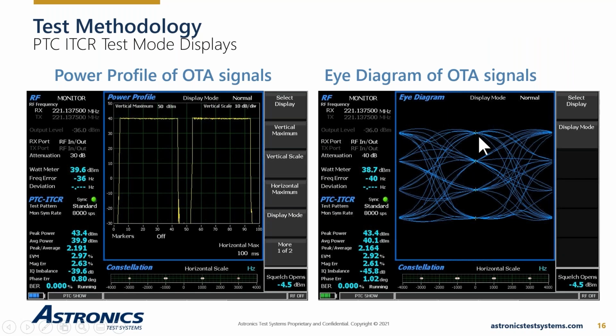Correct. And over here, you were talking about, there's actually 4 decision points. So we see 4 points here, 4 points here, but on the constellation display, we see 8 nodes where the trajectories are. Right. So even though between every shift the physical layer is shifting 45 degrees, the eye diagram is showing you the decision points that the system is actually making its measurement, where it's getting its data from. So basically you've got your 0 0, 0 1, 1 0, and 1 1. So 2 bits on each of these points, and that's the data that's coming into the system.